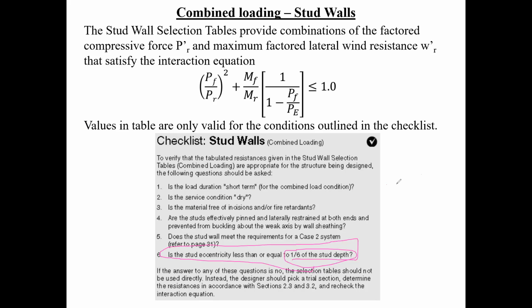And of course, in our case, if this is our top plate, right? Usually you put 2 plates when it's a bearing wall on top and 1 plate at the bottom. That's a typical way of doing it. And of course, if your truss is coming right across here, you can consider it to be concentrically loaded. So you don't have a problem there. In other words, you can consider that you meet it, okay, yes, the answer would be yes to this case, okay?